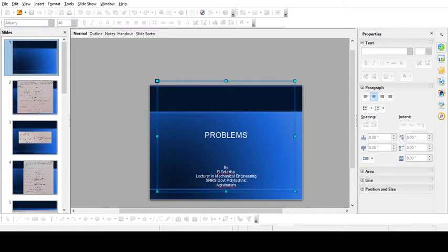So stress induced, sigma, is equal to load by area. The axial load is 1.7 kilonewtons, simply 1.7 into 10 to the power of 3 by area, which is 141.37 mm square.